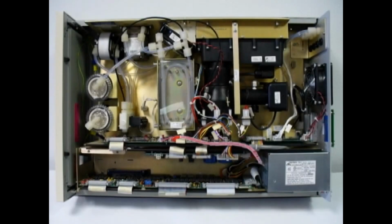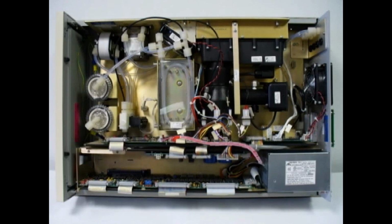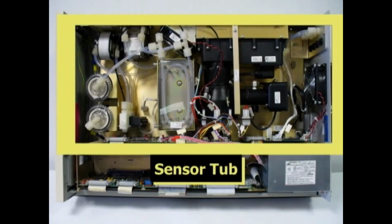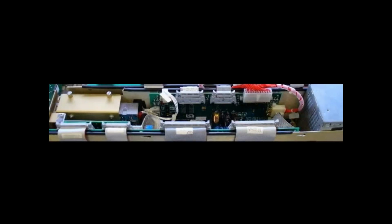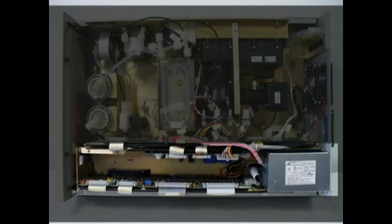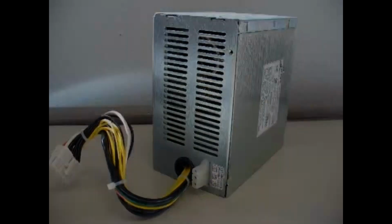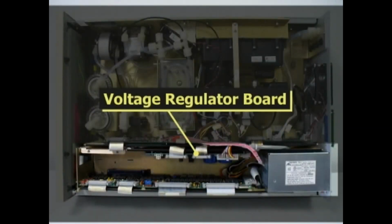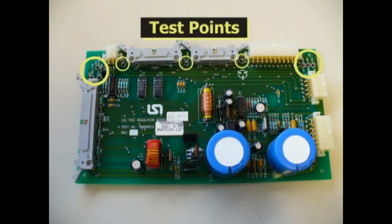All 9800 series analyzers are divided into two sections, the electronics tub and the sensor tub. The electronics tub is the same in each analyzer. The 12-volt power supply is a sealed unit and provides a single voltage to the analyzer. The voltage regulator board accepts 12 volts from the power supply and provides all the power needs of the analyzer. There are test points for each voltage provided.